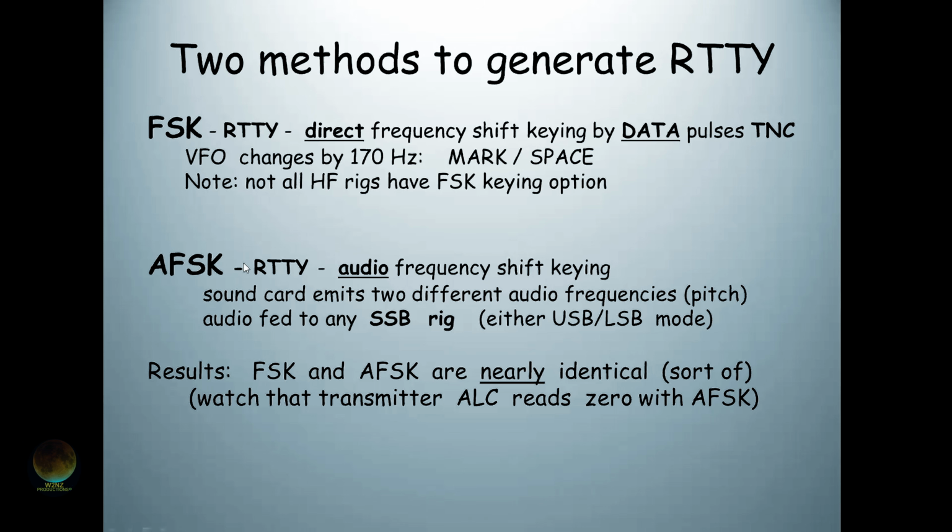Frequency shift key. The other way, and it's much simpler, and actually most of us do it this way: what if I generate the tones in a sound card? That's really easy to do because my computer has a sound card. So I generate the RTTY tones in sound waves. Well, voltages. Now, what if I feed those into a microphone jack of a single sideband radio?